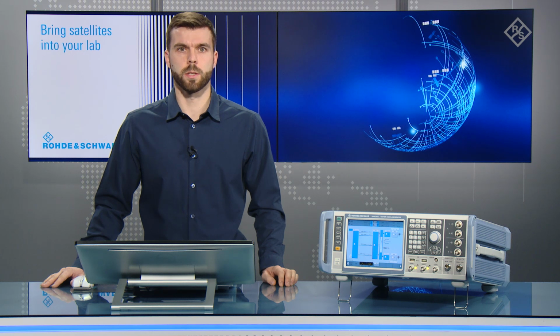So this concludes our episode. You have seen how to add interference sources like AWGN or CW interferers to your GNSS simulation, how to change the parameters of the interference like power level, bandwidth or frequency offset, and how to monitor the signals.